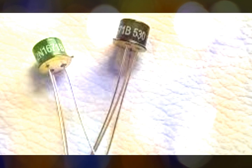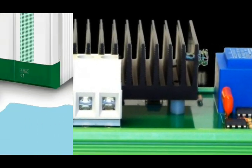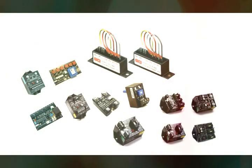A unijunction transistor, UJT, is a type of three-terminal semiconductor device that can be used in timing and triggering circuit applications to control and switch triacs and thyristors used in AC power control systems. Like diodes, unijunction transistors are made of separate N-type and P-type semiconductor materials, with a PN junction, hence the name unijunction, forming in the main N-type conducting channel of the component.